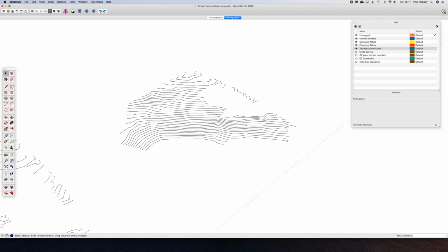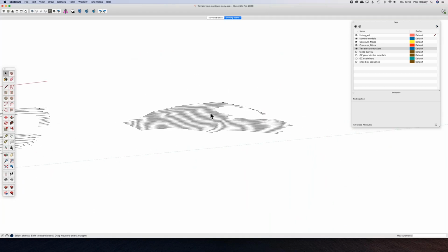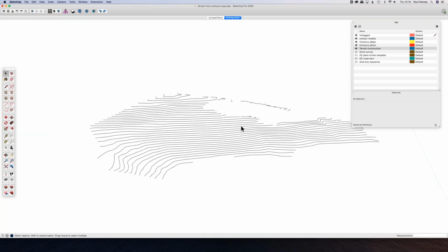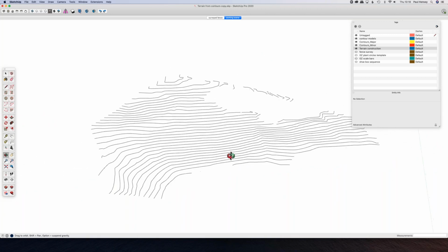And specifically, just to make your life a little bit easier, make sure that you ask for contours that are set on their own layer and are set in 3D. It doesn't take much on the behalf of the surveyor, but it saves you the stage that we may have to go through in a minute. So this is an example of a contour that's come in directly from the surveyor's drawing. I've just stripped out everything else, and I've then taken those 3D contours and brought them into this session of SketchUp.